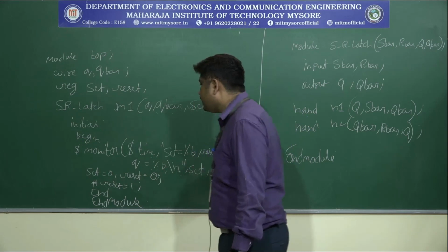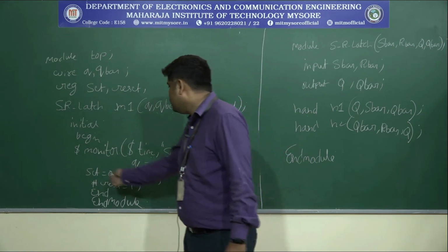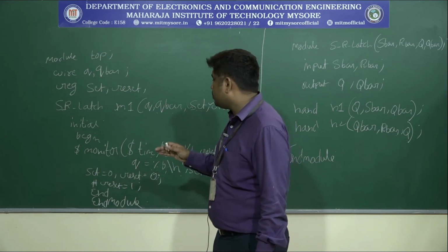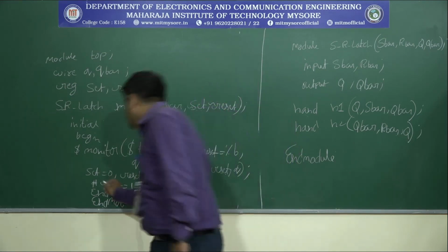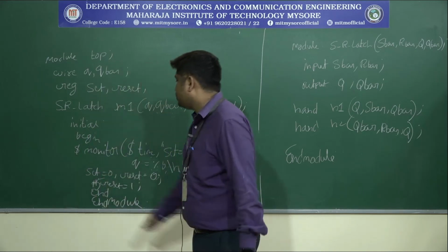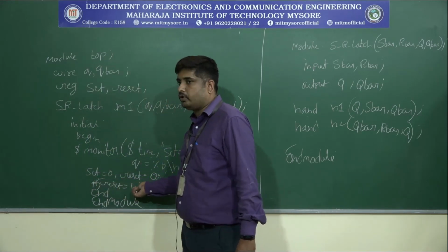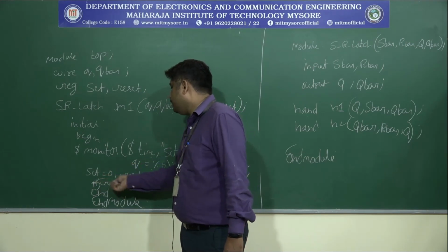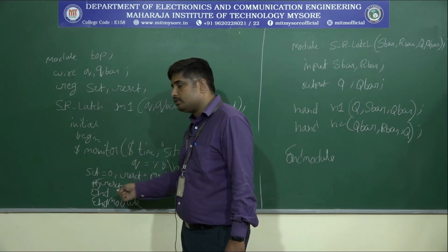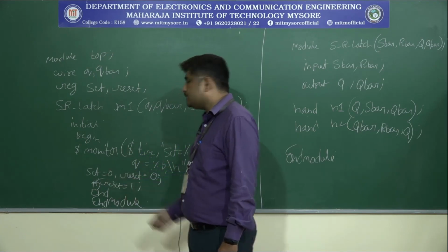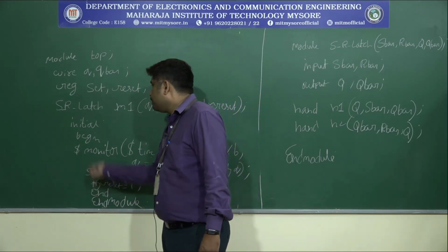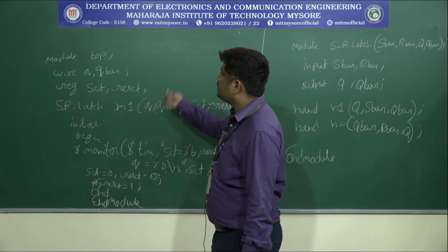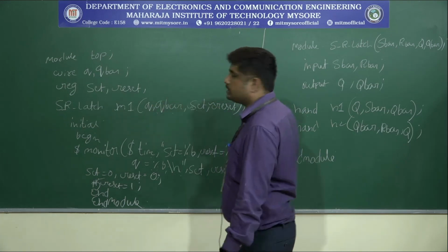Once the monitor is done, you have to apply the data. Initially set is equal to 0, reset is equal to 0. After 5 nanoseconds, reset is equal to 1. So initially 0, 0, and after 5 nanoseconds there is no change in set, it is 0 only, and reset is equal to 1. Then there is end, then end module. So this is a test bench or stimulus program for the SR latch.